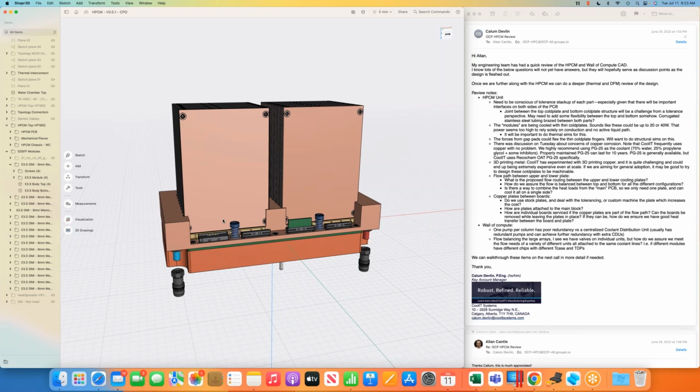Or the data center itself could sit at 65 degrees C, for instance, if no one's going in there. So that's the concept: we put insulation around these chambers to keep all of the heat transfer into the water. You've got maximal capture for energy reuse by getting the water to 65 C. That's the principle of the idea.